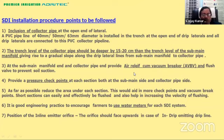And here, mind you, since the drip lines are not visible, as they are going underneath, we need to have appropriate pressure checking points both at the submain and the collector level. It's very simple. You just take a tube out, bend it, and then you can have a portable pressure gauge and check the pressures. So pressure check points are very important.